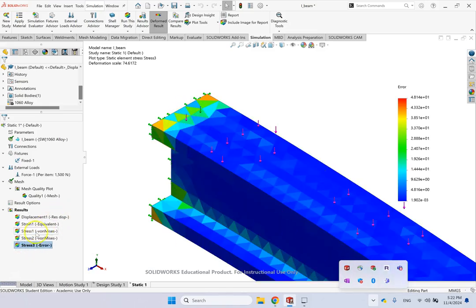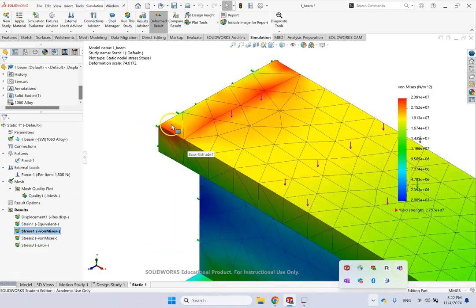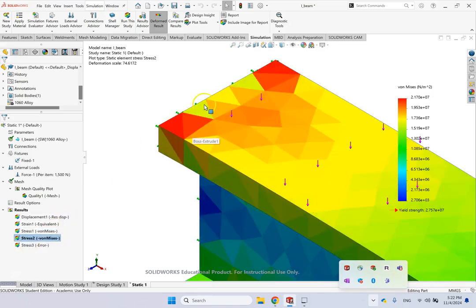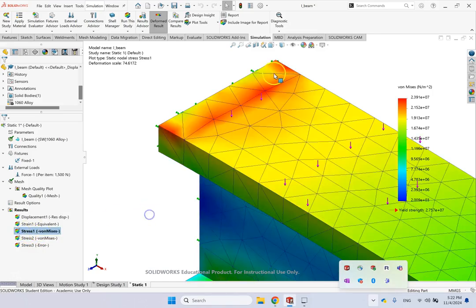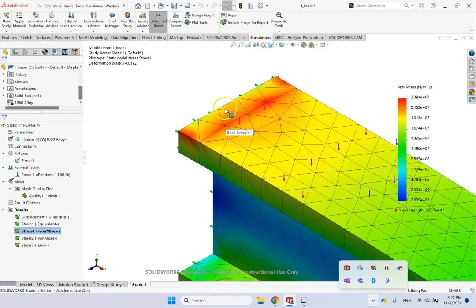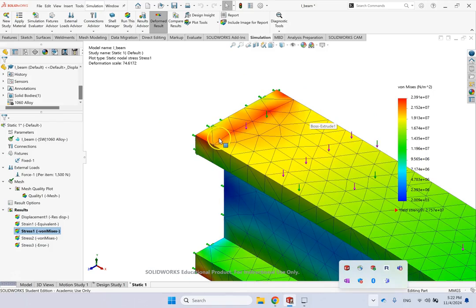But in these regions, right, look at this element and this one, it changes anywhere from red to yellow to orange. But if you look here, these two are red, that one is yellow, right? And then this one is orange. So when this discrepancy, the difference between nodal and element values is high, or in other words, another way to put it is when the discontinuity of this result is large, that is an indication that there is high error over there and the mesh is very coarse and you have to refine the mesh.